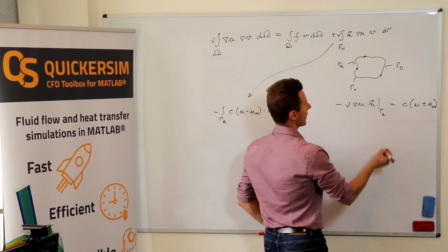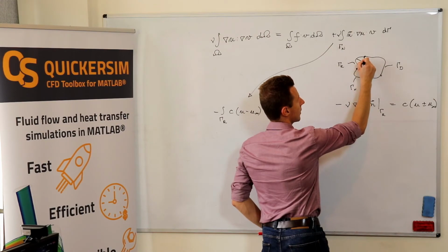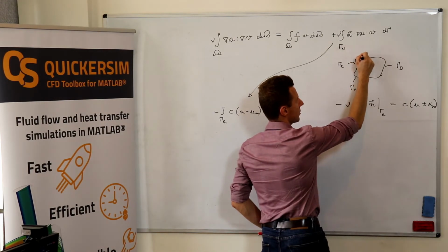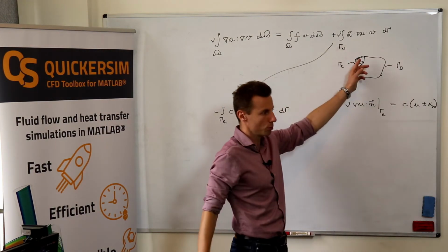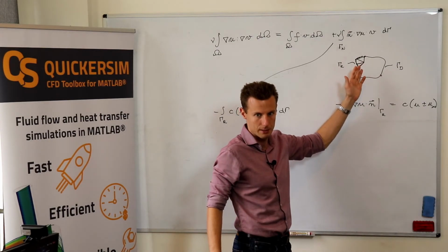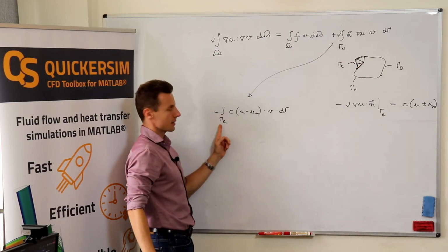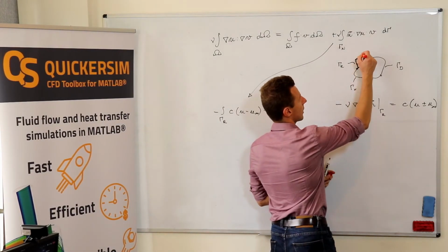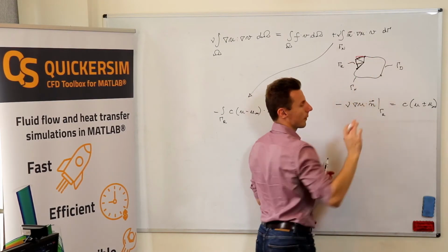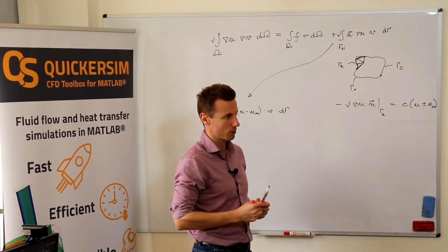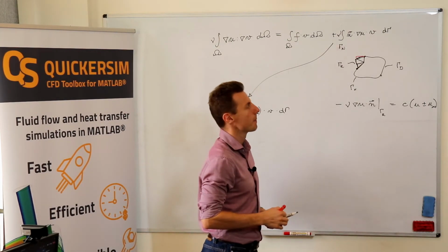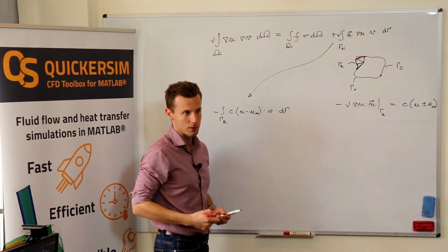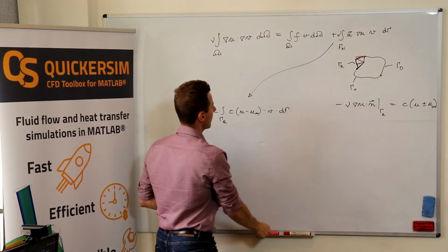So you need to remember that if you've got some elements lying here on the boundary, they do have their two-dimensional shape and test functions, but you're calculating this integral over the boundary, which means that you need to deal with a one-dimensional projection of the two-dimensional function onto the boundary. So you end up with normal one-dimensional shape and test functions of the finite element method.